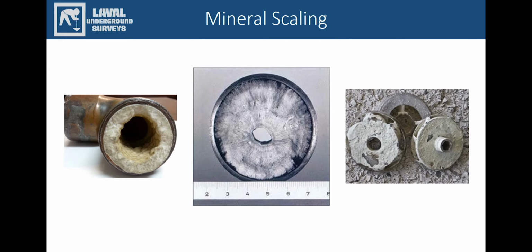If it's placed in limestone, it's likely to have a higher mineral buildup rate because of the solubility of the minerals exceeded. We see this in a state like Iowa, who has high amounts of iron bacteria, but also high amounts of calcium. In order to treat both of these issues, they need to use mineral scale and iron bacteria products, as there's hardly a treatment for both in just one product.